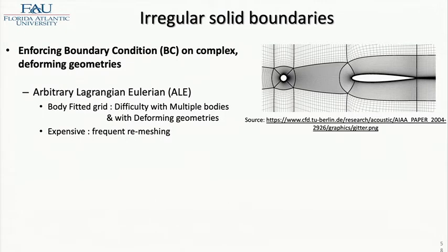And creating these meshes is very heavy computationally. And when you do create a mesh, it often needs manual intervention. You have to go into regions where the mesh might be messed up, and you might have to fix those manually. So if you decide to run an undulating body with a body-fitted mesh, first the mesh would need to be recreated every time step to fit the moving body. And this has to be done automatically. It's expensive, and you're not guaranteed you will get a nice mesh.